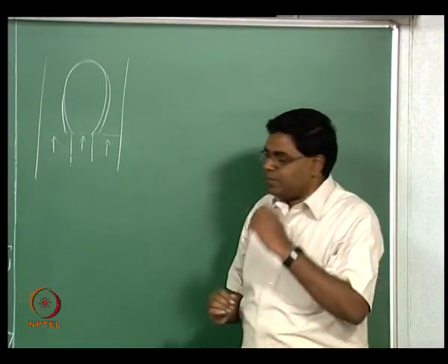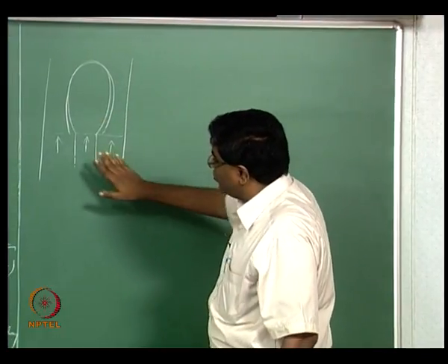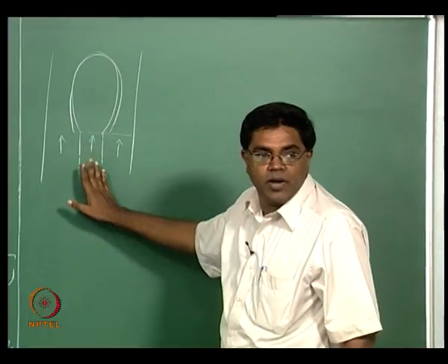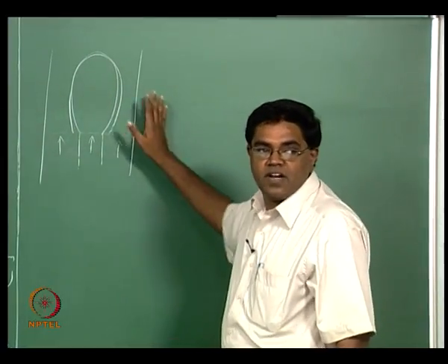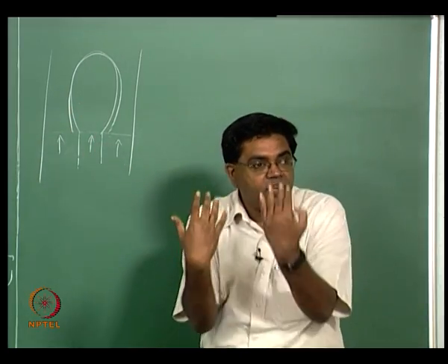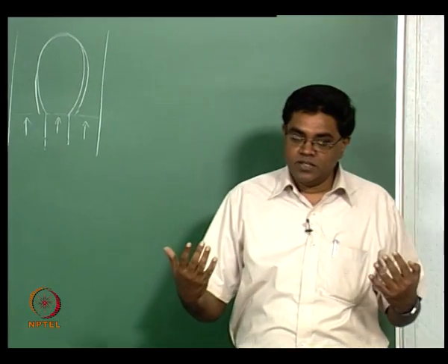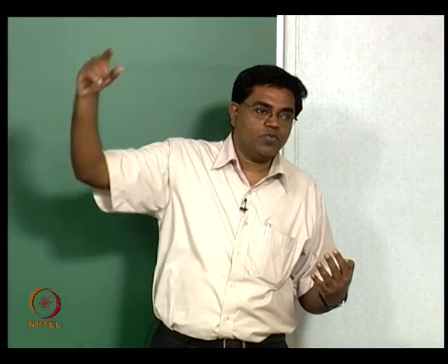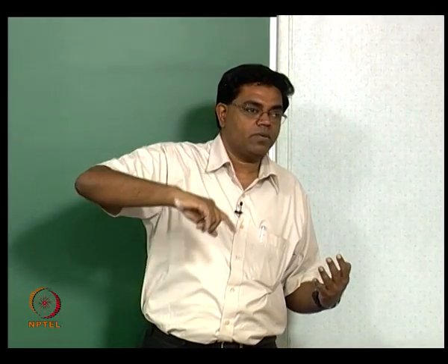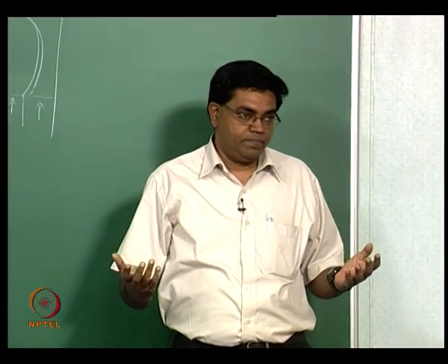okay. So you could now think about a jet flame in which you have only the fuel coming out, you have quiescent oxidizer everywhere, right, and it now gets entrained as well as diffuse, and in this flow field you could now think about wherever the fuel and oxidizer are present in stoichiometric proportions, and that would be your Burke-Schumann jet flame.